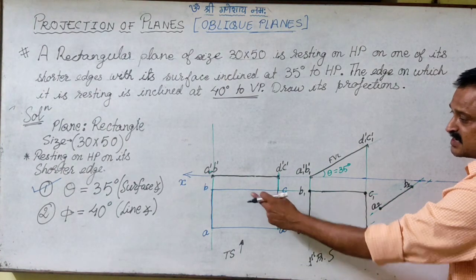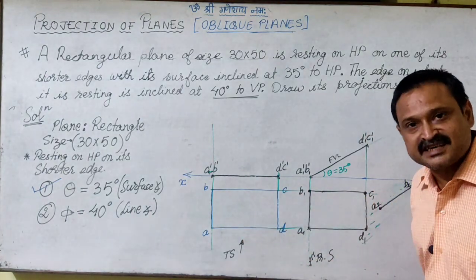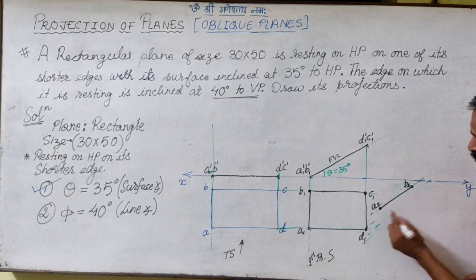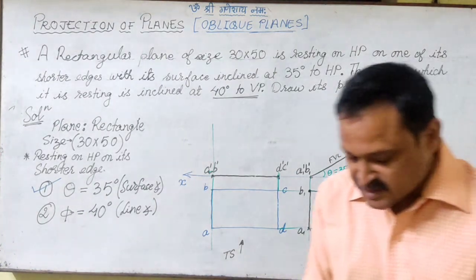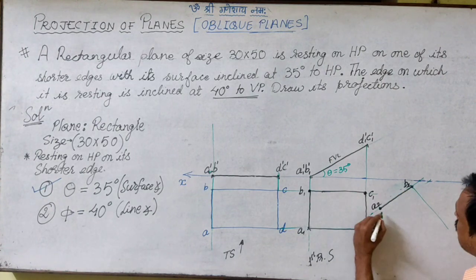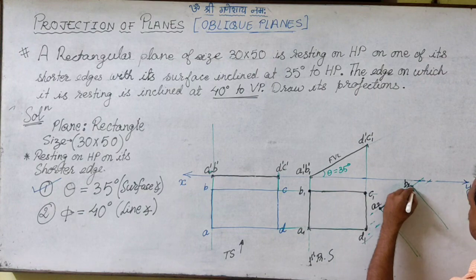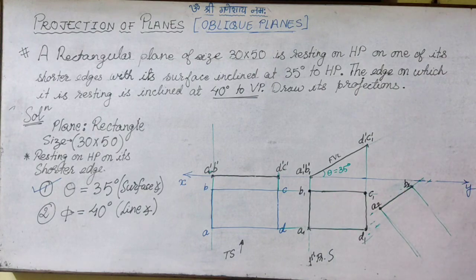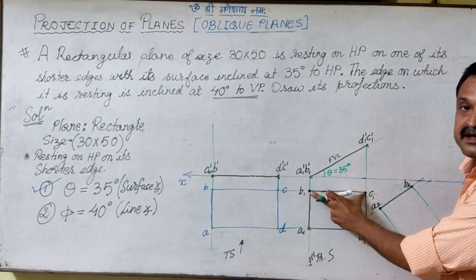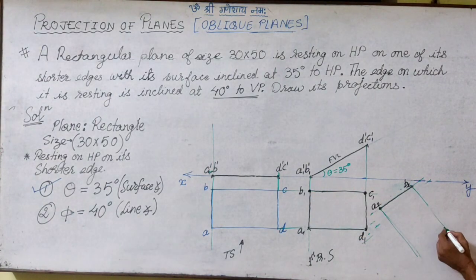Now we know that here the projector and locus are perpendicular to each other. So I can simply, from A2 and B2, draw lines perpendicular to A2, B2. Right? Then I take this projected length B1, C1 in the compass, B2 as center, I cut it.